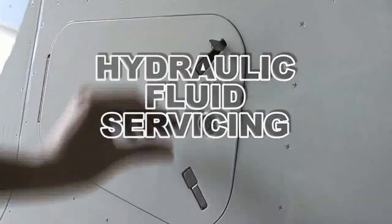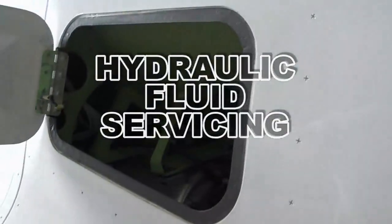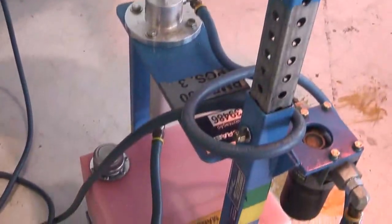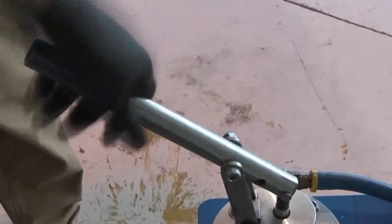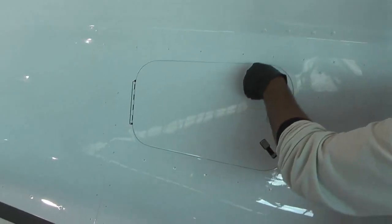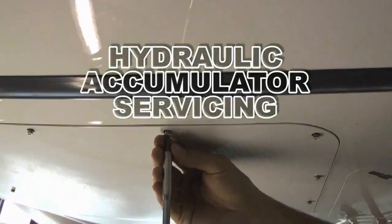Hydraulic fluid servicing. Remove the filler cap. Install the auxiliary hose of the hydraulic reservoir servicing unit to the fill port. Operate the hand pump with an approved hydraulic fluid until the reservoir level indicator shows full. Remove the auxiliary hose from the fill port. Install the cap on the fill port. Close the access door.